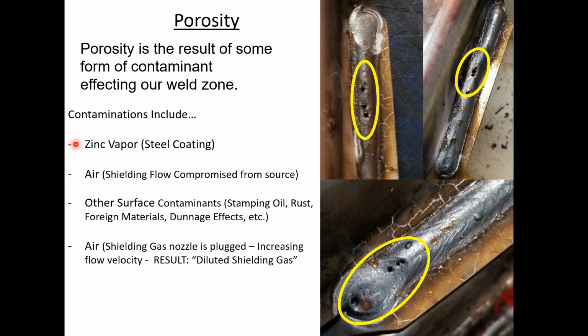So everybody decided pretty much that they're going to start throwing zinc all over all the steel. And this is just basic mild steel, under most cases, but they actually put this coating of zinc on top, which absolutely will not rust under these conditions. So we have to weld through the zinc. Now this is a whole different course, how to go about developing procedures that can weld through zinc vapor.